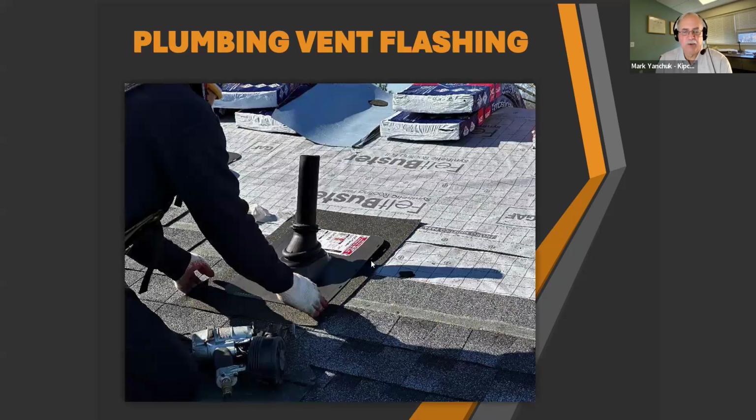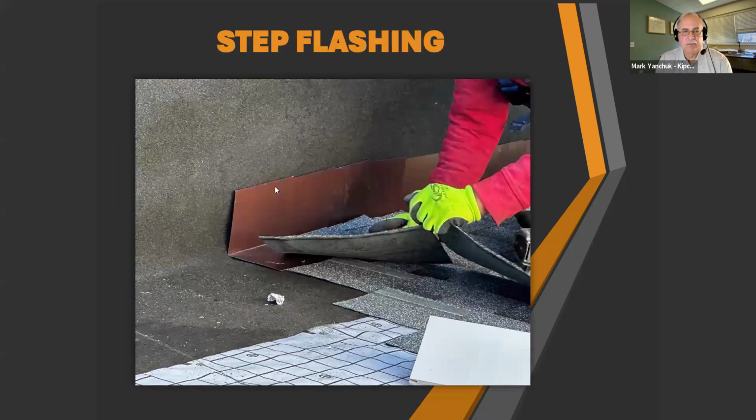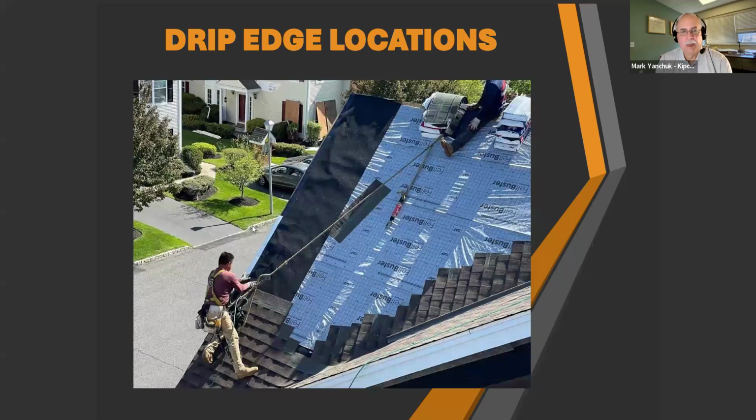Also, these pipe boots have to be done while you're installing the shingles, along with step flashing. This is kind of the end product with the new boot covers on them. Step flashing, the same. They have to be installed while you're installing the shingles. These are just more of the same.